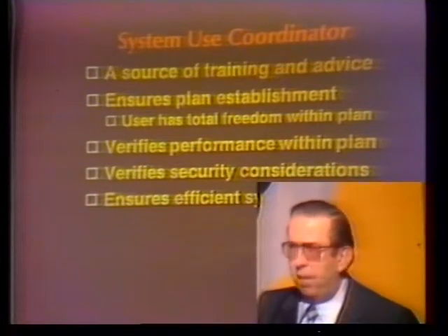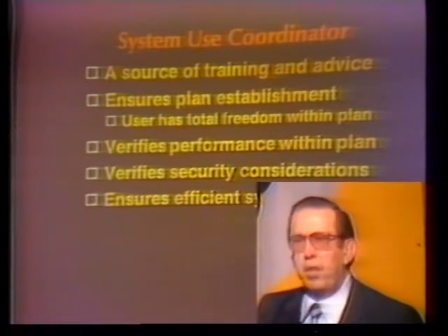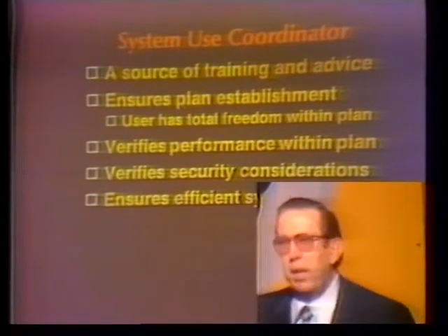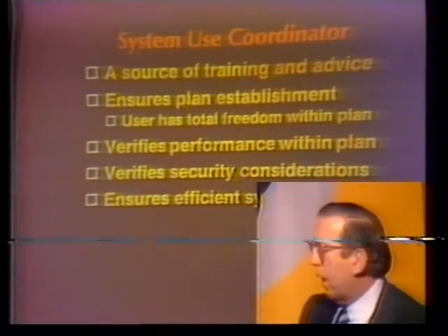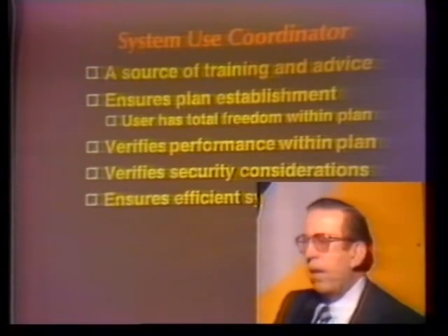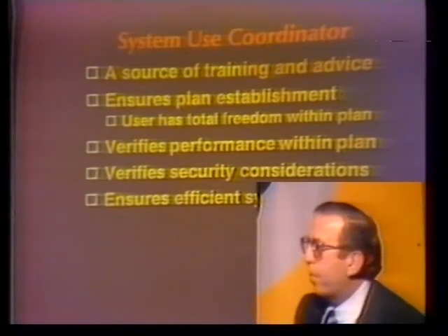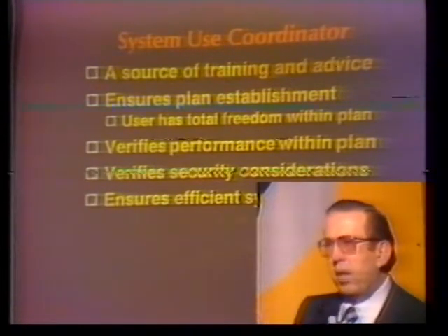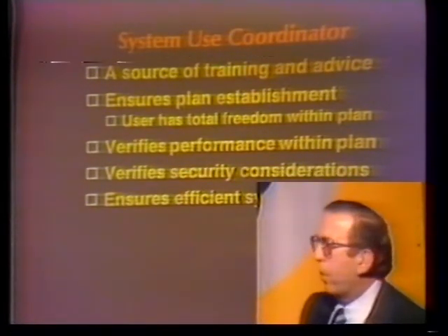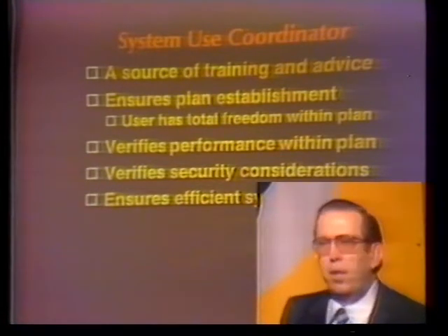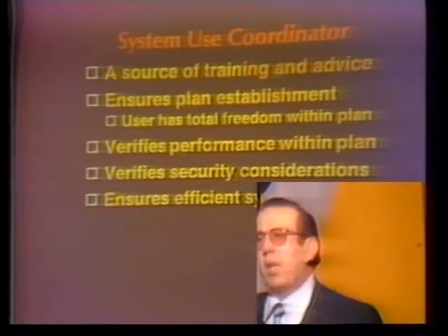A system must have very good security capabilities, and I'm not talking about simple password security here. I mean, sharing a password is pretty mundane, and you can sit there and guess passwords and break most securities. So you need better security methods than that. So things like the ability to assign access to this particular reporting to a certain station by certain users at that certain station, even in certain time frames on that station. And then within the logic of the security controls, you can build up all kinds of mysterious algorithms of password changes. In other words, the password can be constantly changing based on some kind of algorithms.